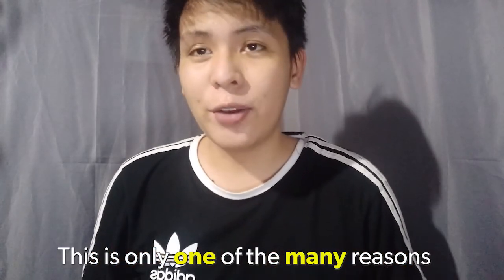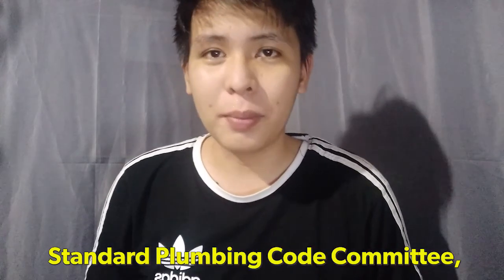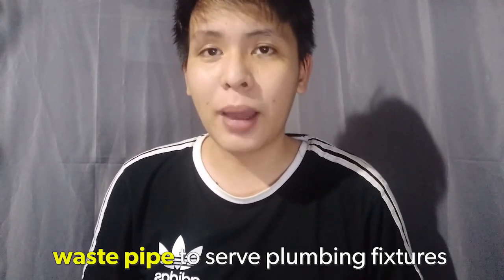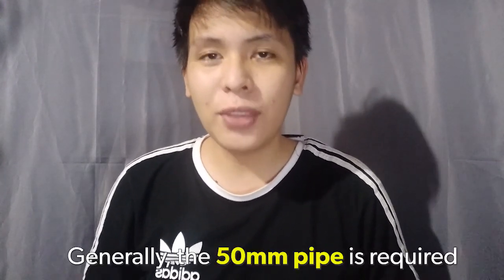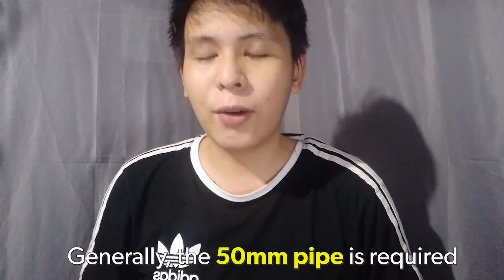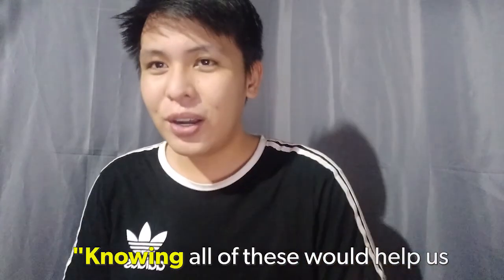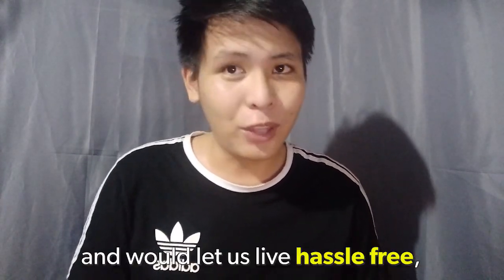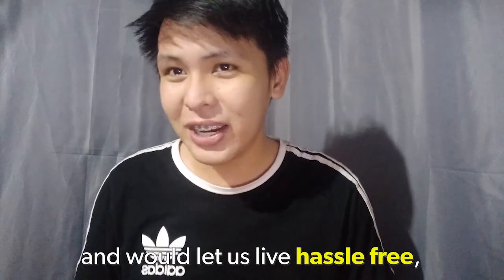This is only one of the many reasons why the Standard Plumbing Code Committee issued limitations on the diameter of the waste pipe to serve plumbing fixtures. Generally, the 50mm pipe is required for all the types of urinals. Knowing all of this would help us to avoid our pipes being clogged and would help us live hassle-free.